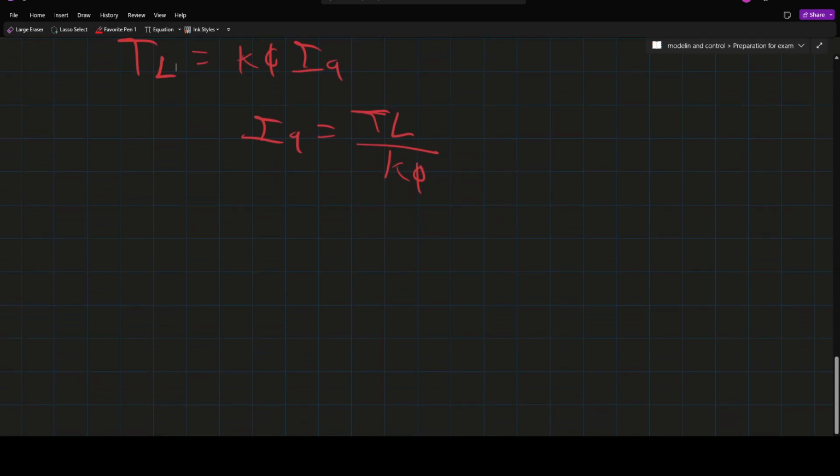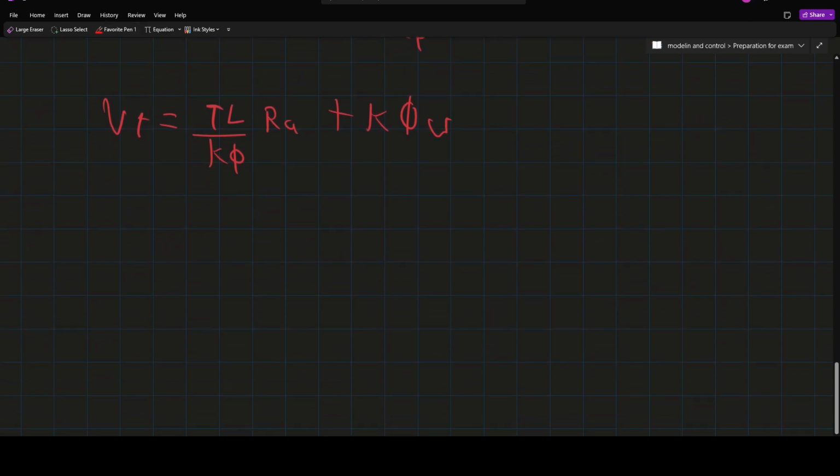So we are going to have Vt equal to TL over K phi times Ra plus K phi omega.